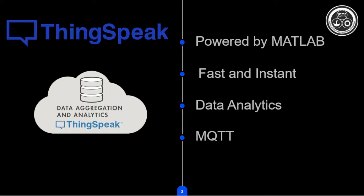Now this topic temperature is created by the NodeMCU, or created in the ThingSpeak server, and the ThingSpeak server itself is a subscriber of this topic, and our NodeMCU is also a subscriber of this topic. So we can call it a client. Our NodeMCU client can send data to the ThingSpeak server, and the ThingSpeak server can read the data obtained from the NodeMCU. This is how MQTT works, and Facebook initially used this MQTT protocol in their messenger. This is just for information.